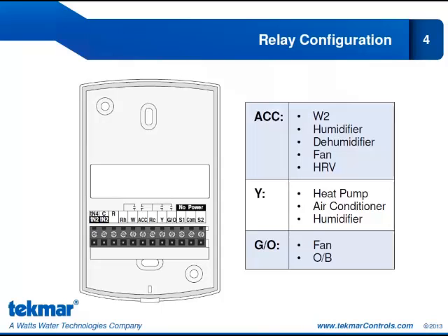Our GO relay can be set to operate a fan, or if you're using a heat pump, it would control the reversing valve. We will review this relay configuration later in the presentation.